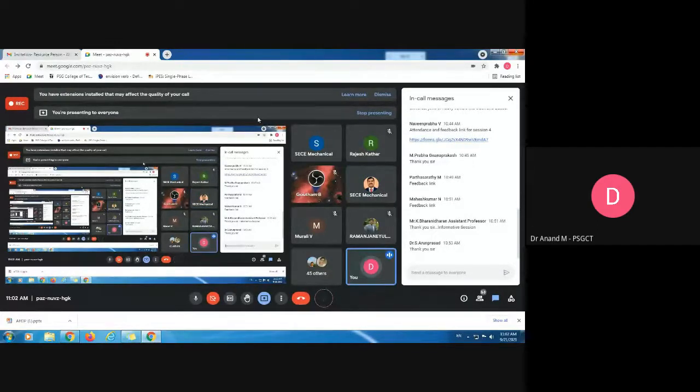As far as the power modulator is concerned, we have speed control precision, whether based upon a sensor-based technique or a sensorless technique. The advanced technology we use is a sensorless technique using state estimation, instead of depending upon the conventional sensors mounted in the stator of the motor. By predicting the current, voltage and frequency patterns available to the stator winding, we can do model predictive control and adopt a sensorless technique, which is a recent development available in power modulator stages.